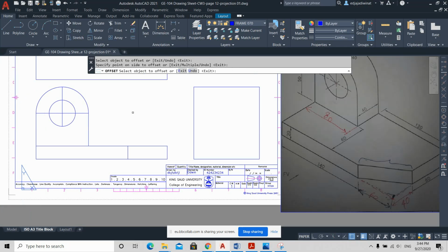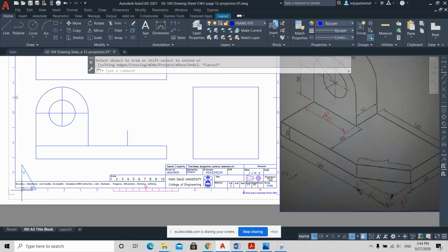Of course, you can use the UCS command to do that. I'll show you for once, just to refresh your memory. I'll delete this line, or I'll just bring this line up. I'll turn on the ortho mode. I'll bring this line up. I'll trim this just to show you that the result is the same. So this is the coordinate system. The 0, 0 is here. I will move it, for example, to this corner.